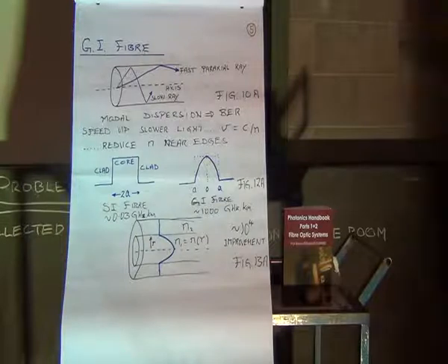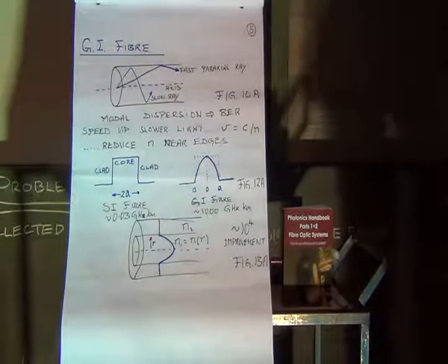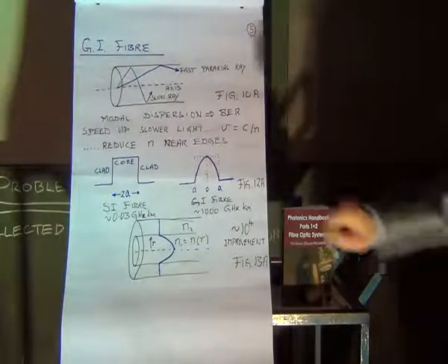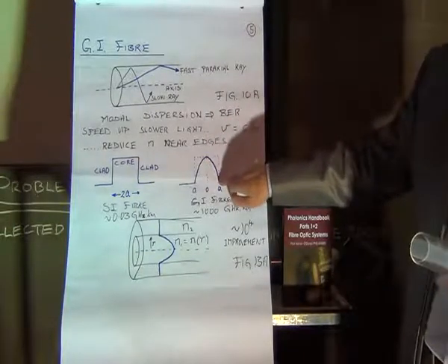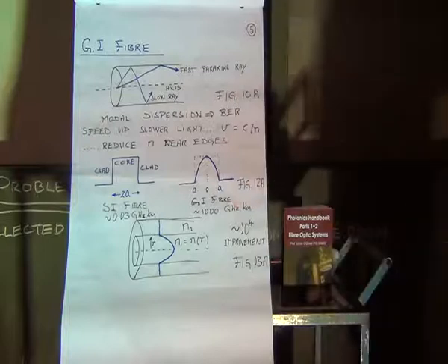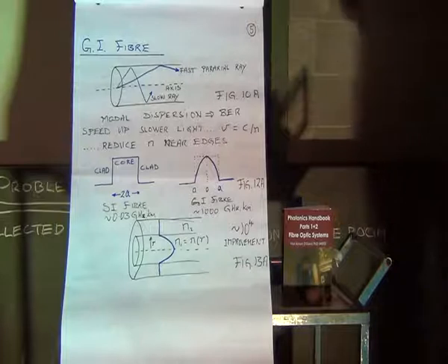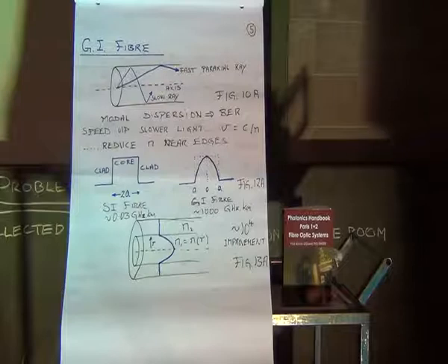Now, from the point of view of growing that thing, all we've got to do is make sure the preform, as we inject the gases, what we need is a computer-controlled set of valves. And we write a program to open and close the valves in such a way that the dopant gases gradually change the refractive index at a desired rate. Okay? So that would have made a very nice PhD project somewhere like the University of Southampton 20 years ago.